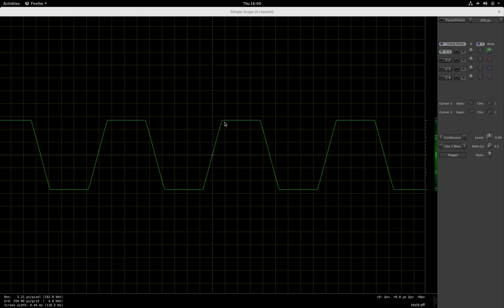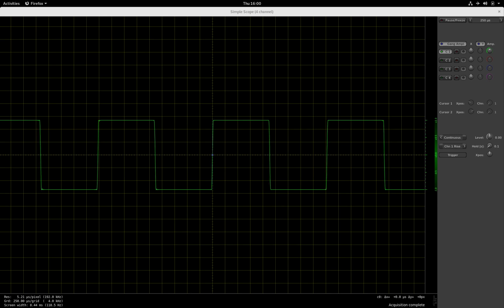The output voltage will only get to a certain point where it hits the supply voltage, and then it can't increase anymore. So it will just remain constant until it drops back below the supply voltage. And the more we increase the gain value, of course the stronger the clipping will be. We're now at 30 decibels, and we have basically turned our sine signal more or less into a square wave.